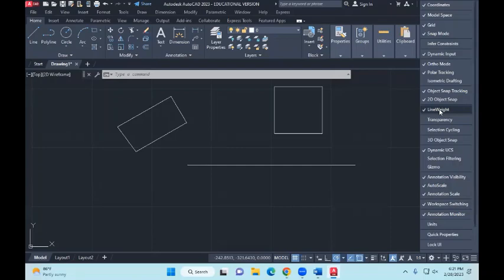You might have come across the term like construction lines, isn't it? What are those construction lines? Light. Okay, just construction work. Then you have outlines, isn't it? Another type of line is what? In engineering drawings. Yes, the dashed ones. Yes, hidden lines. Another line to indicate centers of circles or concentric shapes. Those are called center lines, exactly. So those are different line types.